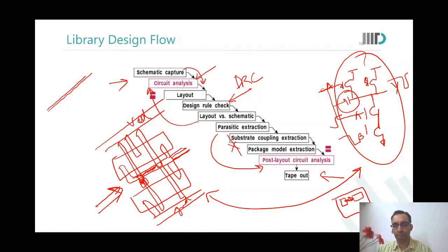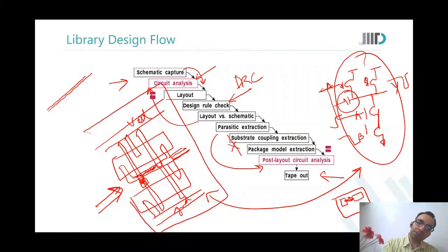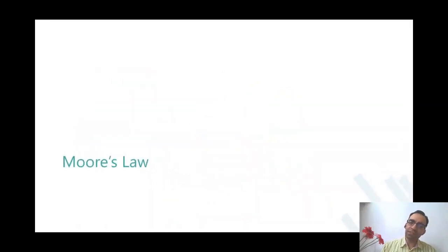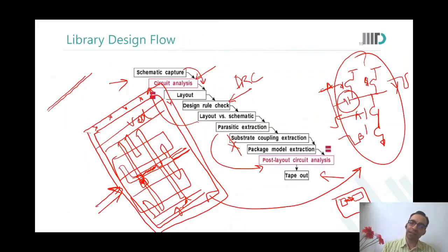And how do we solve these problems? We use things like guard rings. Let us say this is your NAND gate, and this is some analog circuit. Around this analog circuit, I will make a ring of substrate connections. If there is any noise coming from anywhere else, because this ring has all VDD substrate connections and ground substrate connections in it, this ring will sink that current. It will not let that current spoil the behavior of the transistors enclosed within it.